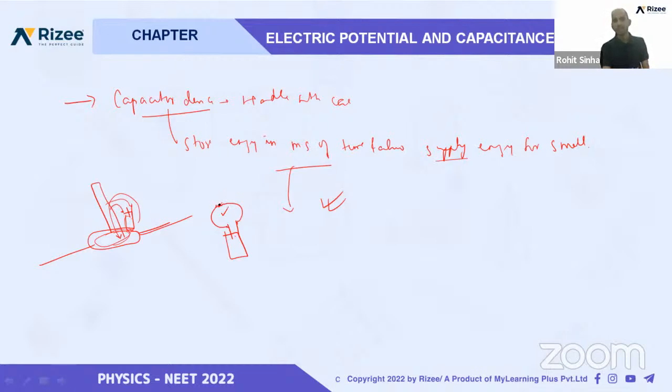When they touch the two wires of the capacitor, they make the capacitor charge 0, and after that there is no danger from the capacitor, because from a capacitor we can get a sudden shock. Sudden damage can occur. That's why we first discharge the capacitor.